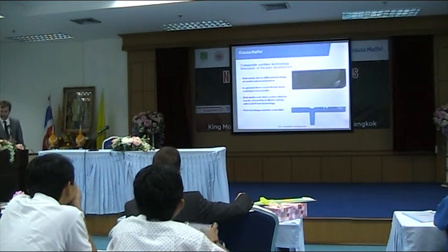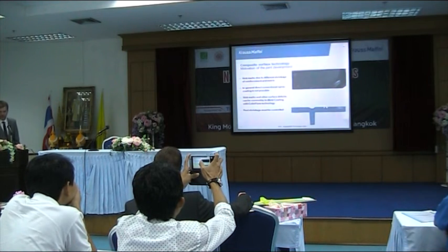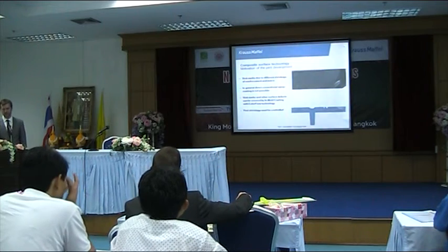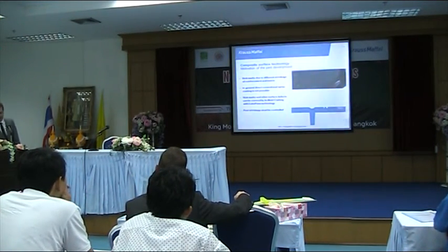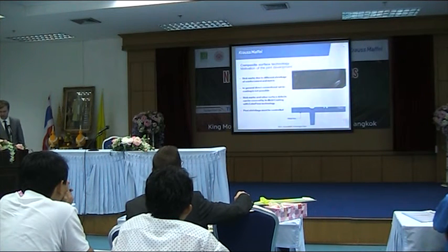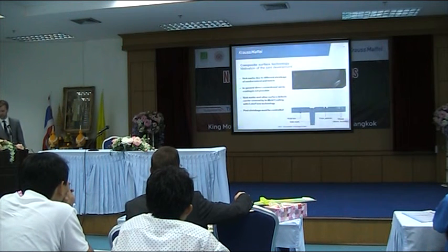So you have sink marks due to different shrinkage of the reinforcement and of the matrix also. So in general, you cannot use conventional spray painting on the surfaces. So now this is about surface resin transfer molding. And if you have sink marks and other surface defects, like weld lines, pinholes or streaks, you need a coating.